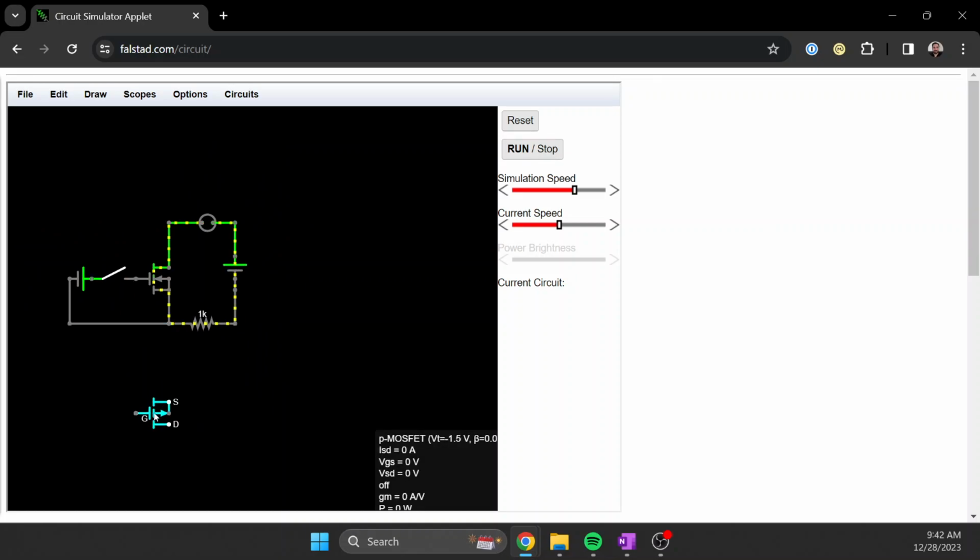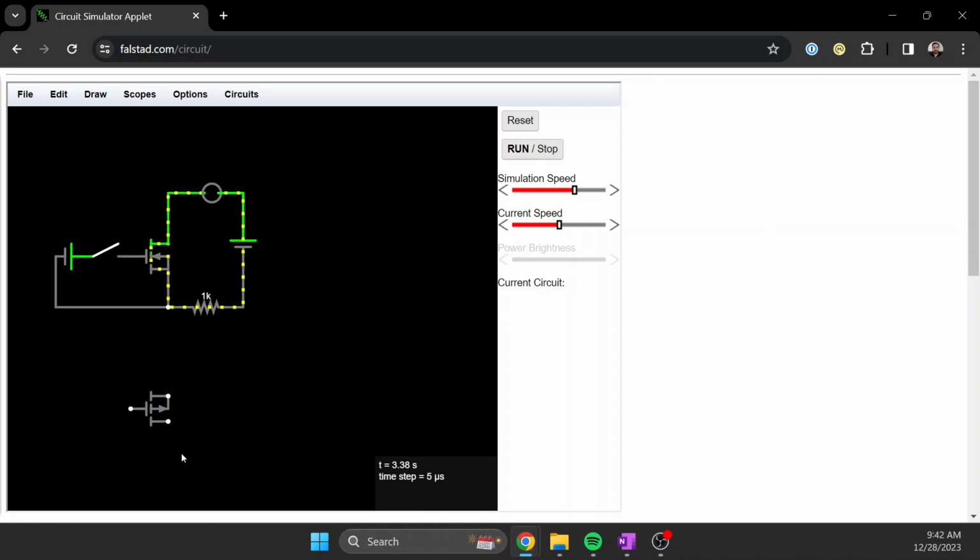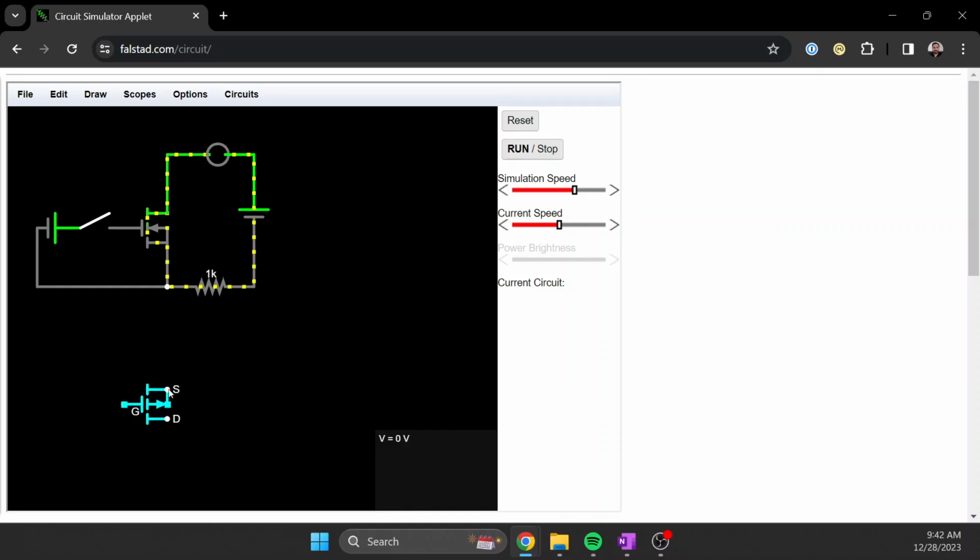And we're going to contrast this with the P-channel MOSFET down here. Again, my source is at the top, the drain is at the bottom. So in a lot of ways, it's going to look like a similar circuit because the source has to go to positive in P-channel. So the MOSFET is flipped, not the battery. Whoops, wrong. So I'll draw a wire going up. I just press W to add in a wire. L for another LED.